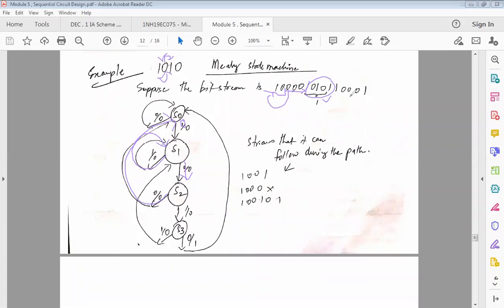Similarly, since at 0 my stream of data is not happening, ultimately your target should be only this binary number 1 0 1 0. Wherever you get this sequence, just connect the graph there. So I have 1 0 here. Now with 0, I do not want a 0, but after 1 0, I actually want a 1. So what I'm doing is connecting it from here to here.